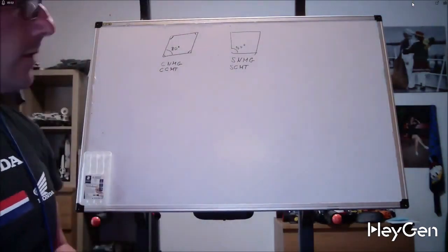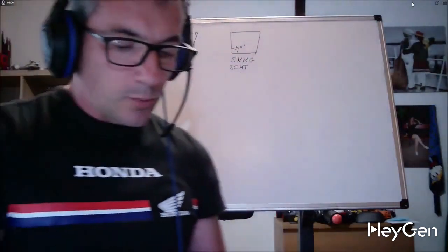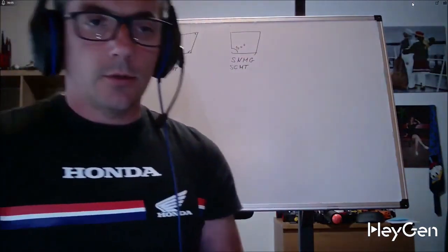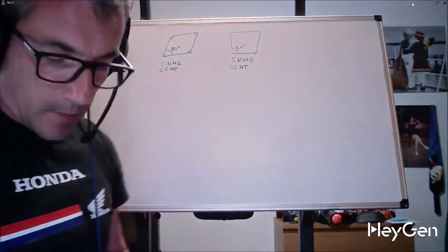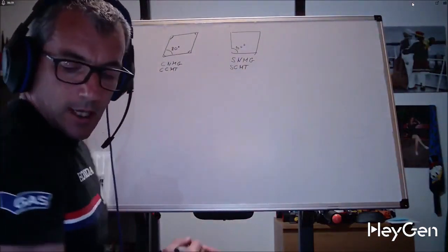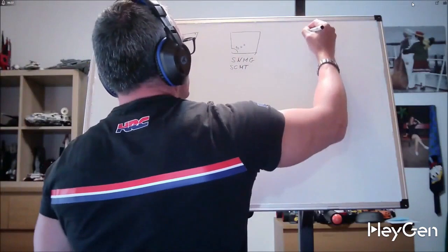Okay, for every type of turning insert there is always its negative version and its positive version. Negative is preferred for roughing operations which require sturdiness, while positive is preferred for finishing or soft material. For example, with aluminum we only work with positive inserts, except for a few exceptions. There is always an exception that confirms the rule.